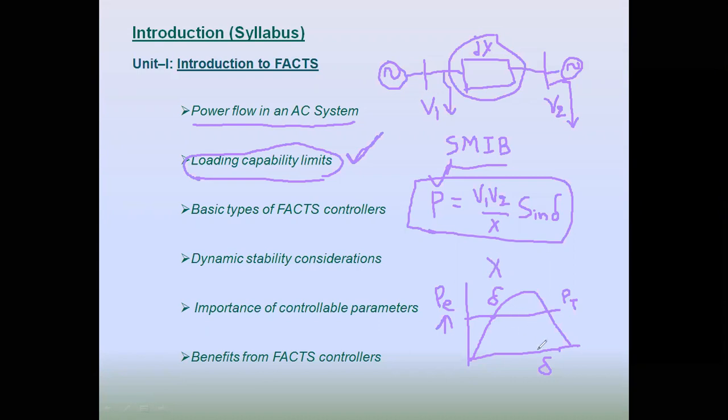That depends on the critical clearing angle, at what time you are clearing the fault. Many things we study later. For example, if you clear the fault at this point, later we'll discuss different analysis. We calculate the areas in the normal condition, that is before the fault occurs, and the swings we consider along the equilibrium point, whether it comes to the stable point or not. We'll discuss further in the later sections.